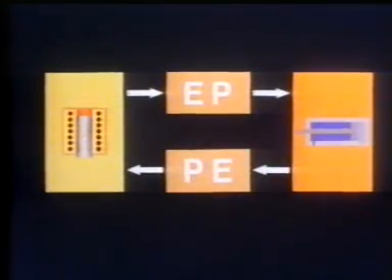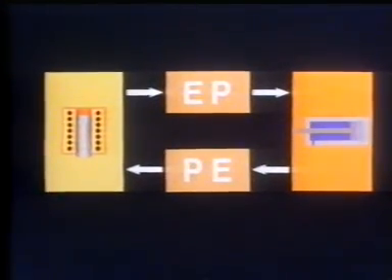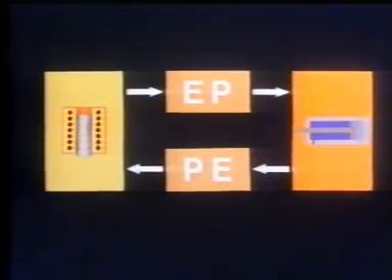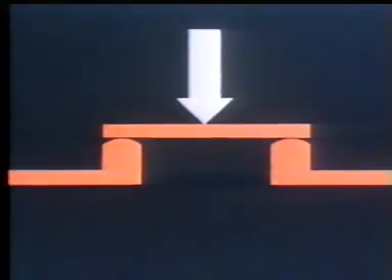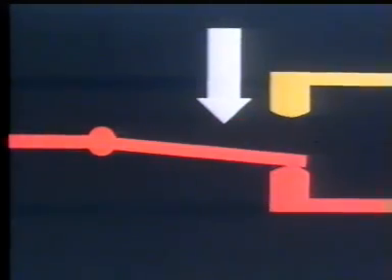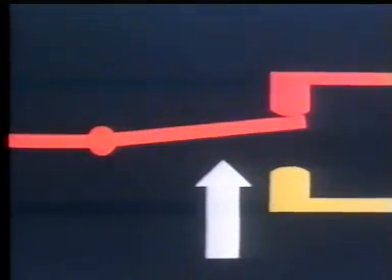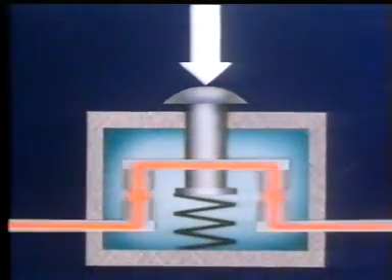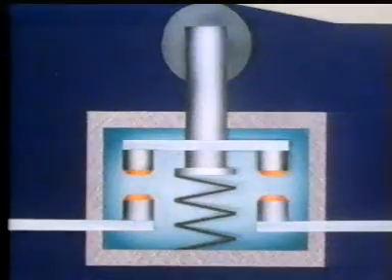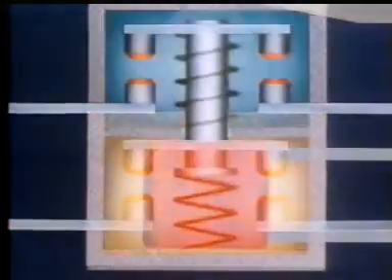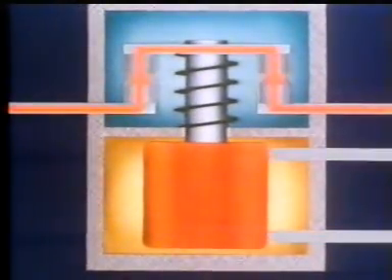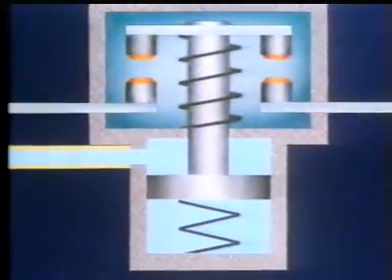Signals are transmitted in the electric control circuit by means of switches and contactors. Switches and contactors close contacts, open contacts, or change contacts. There are a number of types of operation to execute these functions. Manual, mechanical, electrical, pneumatic.